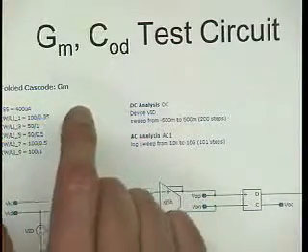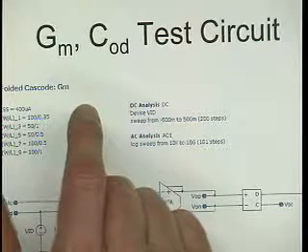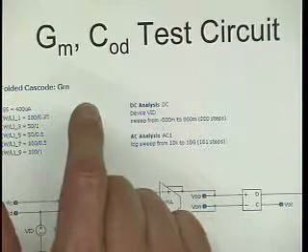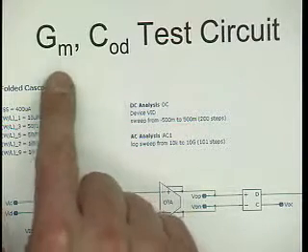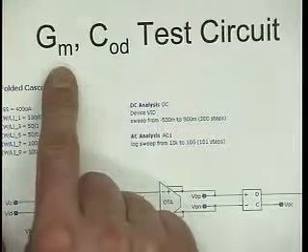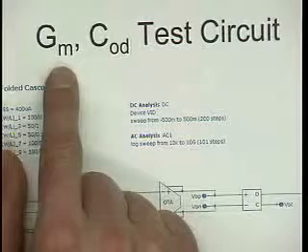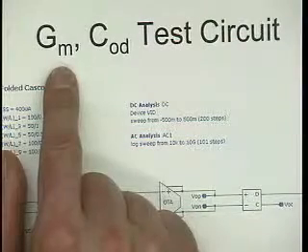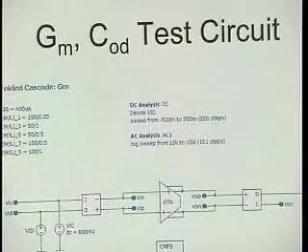And then we go and figure out what the bandwidth is of our monster amplifier, and we find that it's short. Well, there are lots of possible reasons. One of them is that GM could be smaller than we actually had designed for, for whatever reason. But then we go and track down that reason. But if we don't even know what GM is, we only know what we think it ought to be, we may run around in the dark for a while.